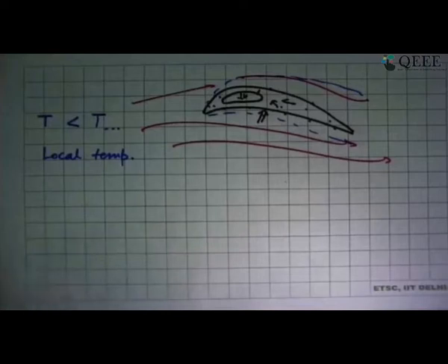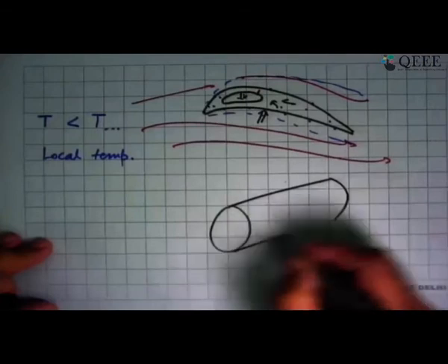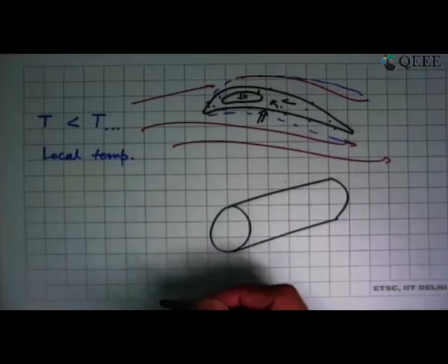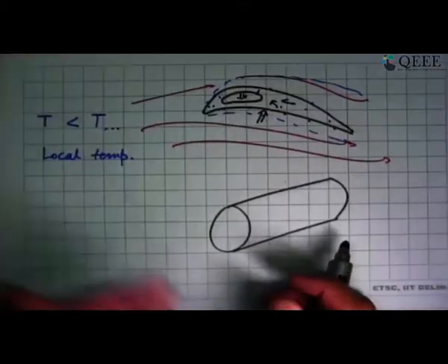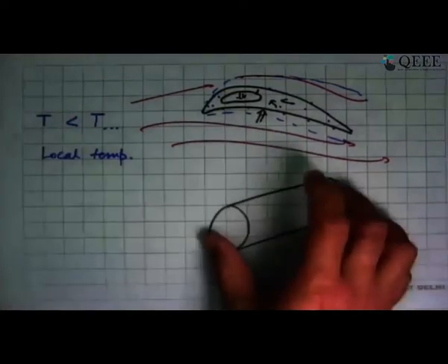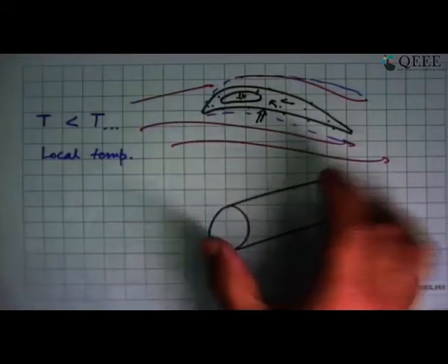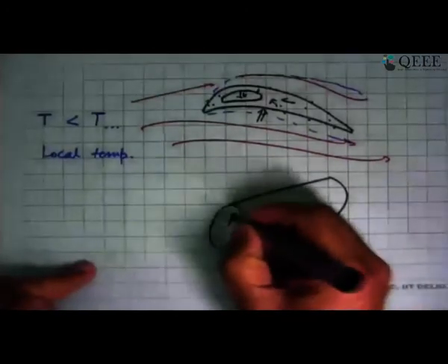Another example, say from manufacturing, would be that we have a part which has been forged, or we want to heat treat it, say a piston pin. So you have heated this, and then we suddenly dip it into cold oil or cold ambient water. If this has been heated to 600 degrees Celsius and then plunged, we know that suddenly you have vigorous boiling and all sorts of things taking place. And there's heat transfer happening through this, and then inside this also by conduction, heat transfer is taking place.